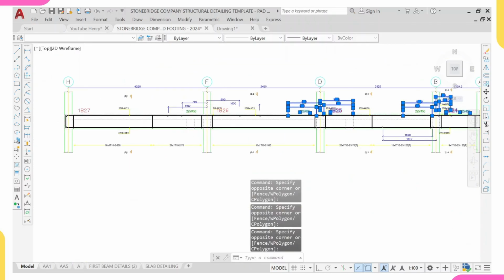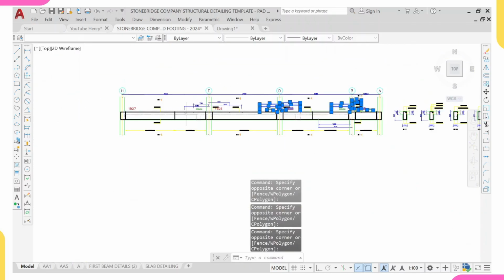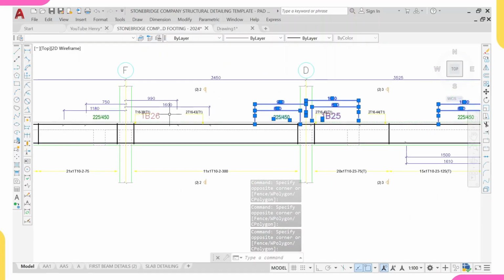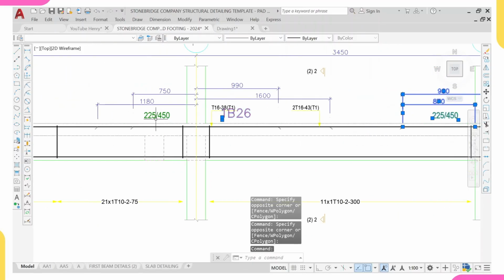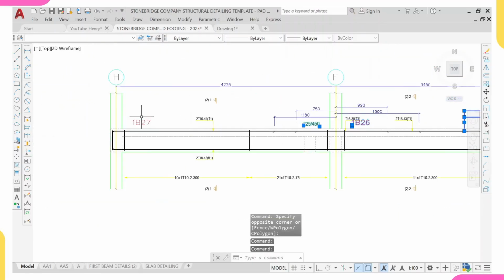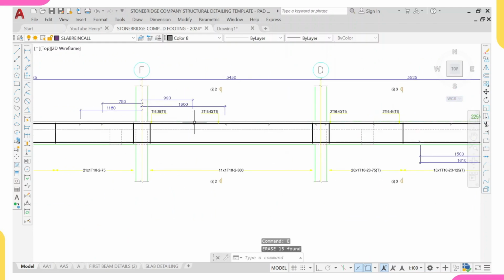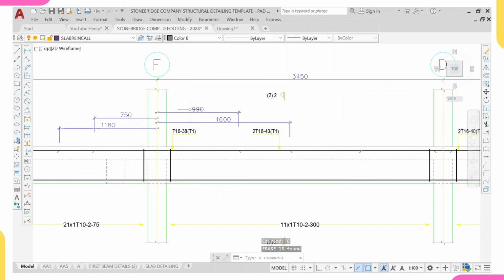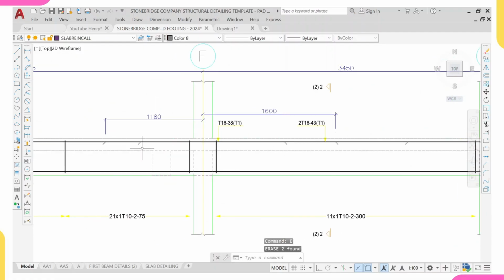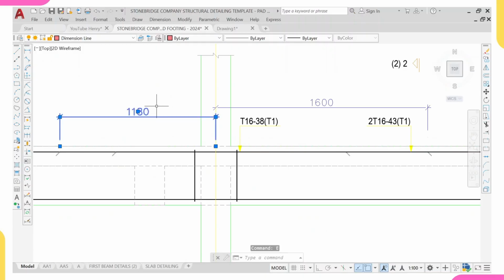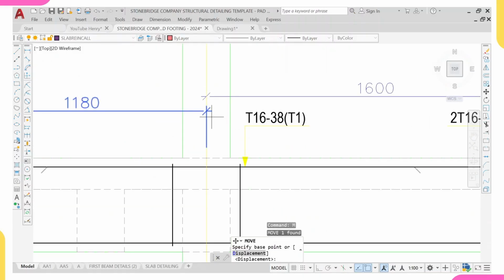This is the point where we're having top reinforcement. So I'll just erase this, also erase this, and also come over to this point and erase this. I'll do enter, so I'll have a neater drawing. So that top reinforcement runs from this point to this point, but I'll show you how to go about it now. I'll do enter. I'll write these two things to be together.